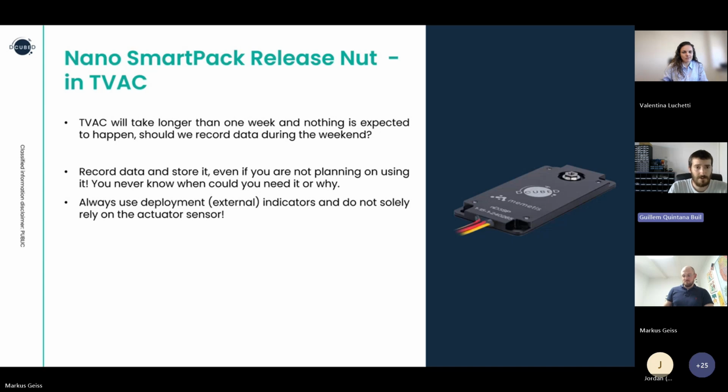And the same goes for vibration. We have also seen some companies that, for saving time, especially because the availability of test houses is rather limited, and we understand that once anyone gets a booking for a test house, you want to make the most of every single minute there. For that reason, we've seen companies avoiding doing resonance searches between the excitation runs. But sometimes, if there's mechanical damage on the payload, they are not noticing.